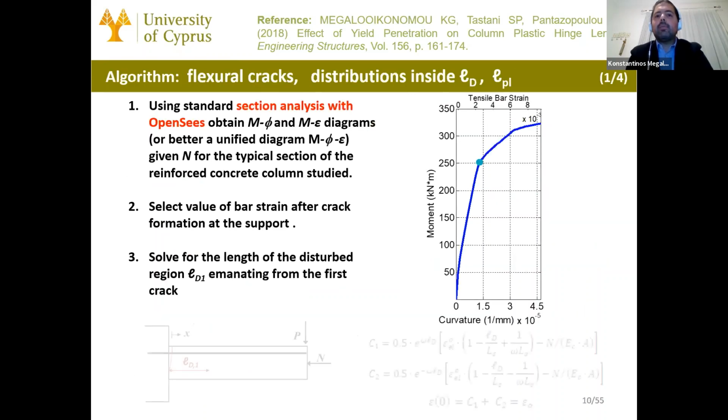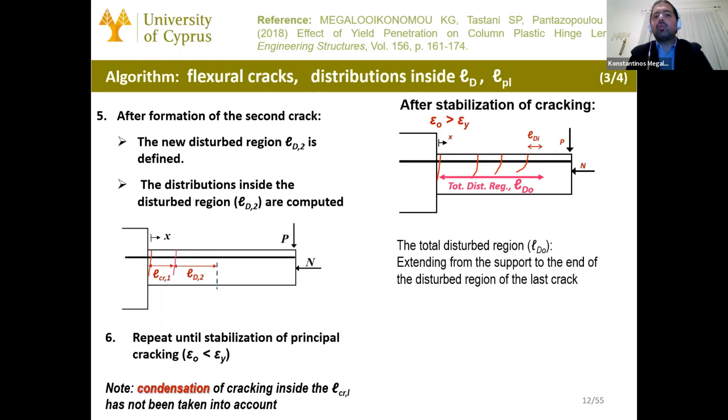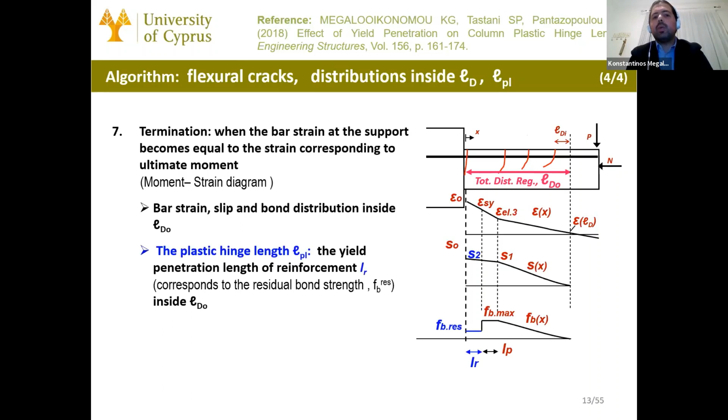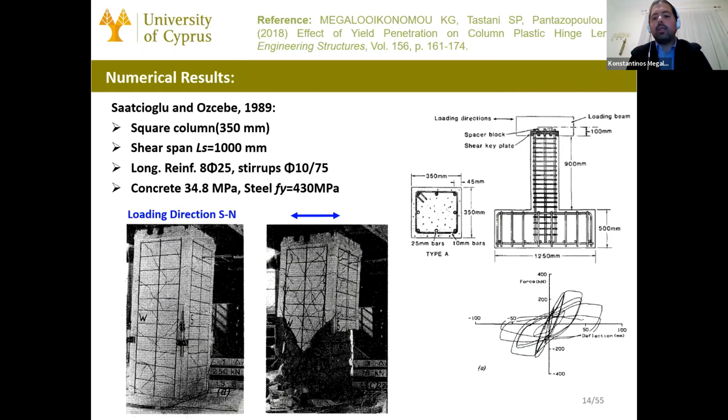I can imagine that curvatures from opposite sides of the column can be measured, and the shear strain with X-shaped linear transducers, and you can define that during the experiment.